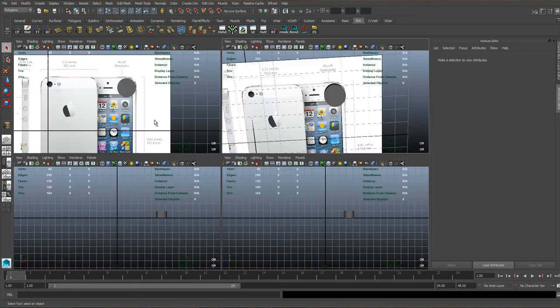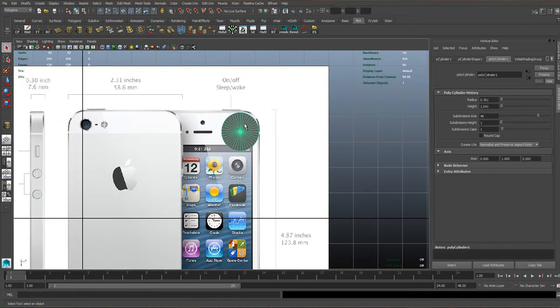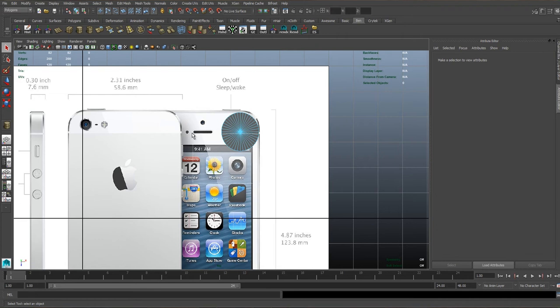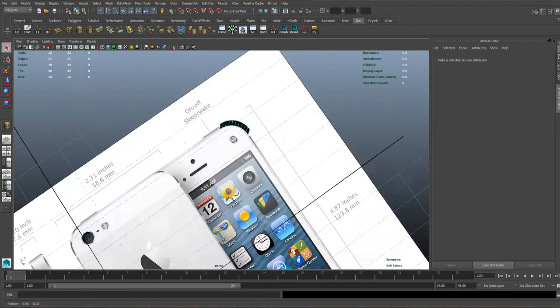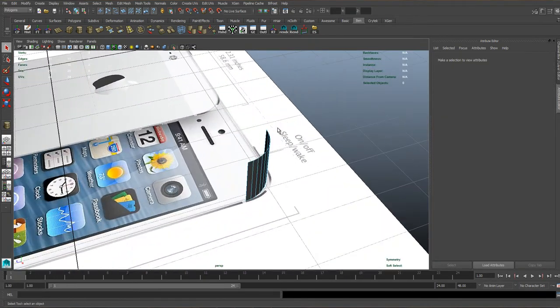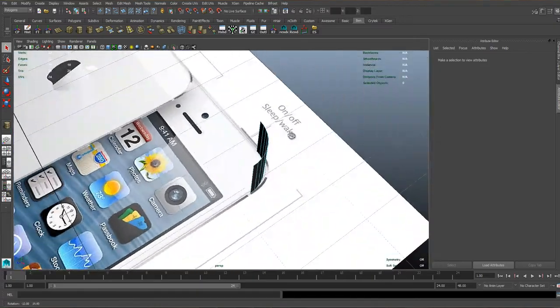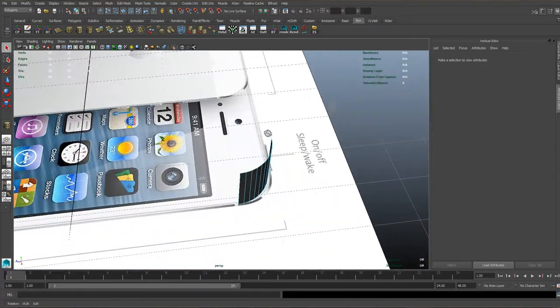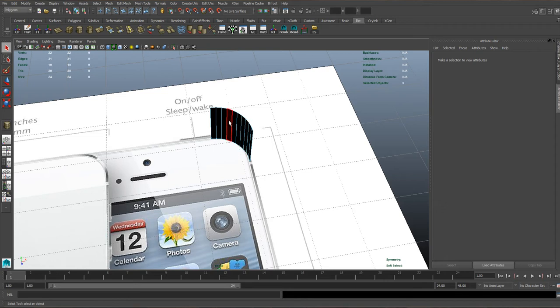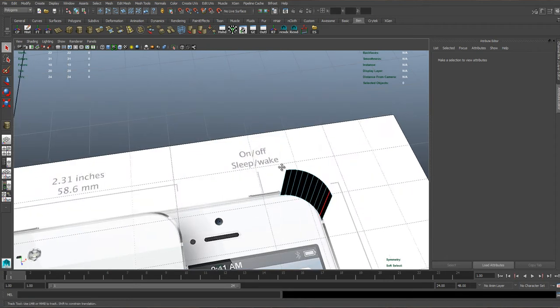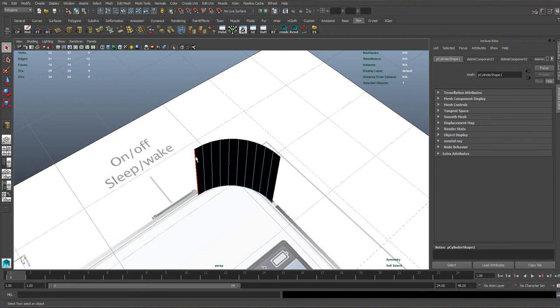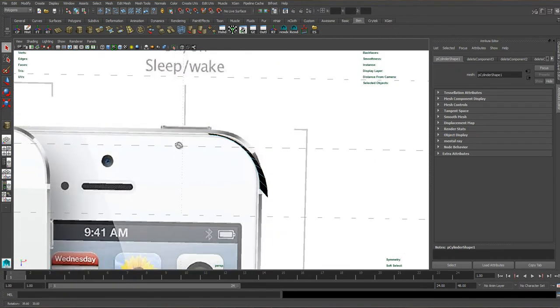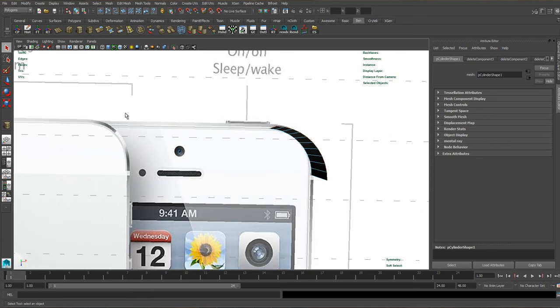And then jump to my top view, and I'm going to select the cylinder, go to Face, and delete everything I don't need, which is all of this. And I should just be left with the top right hand corner pretty much of that cylinder like this. Once you've got that, I'll go to Edge, and I'm going to select only these edges, these ones along the top and the one along the left side there, and I'll go to Extrude.